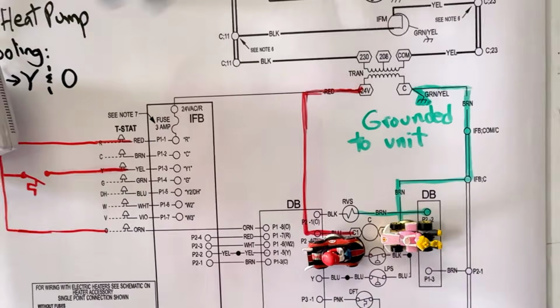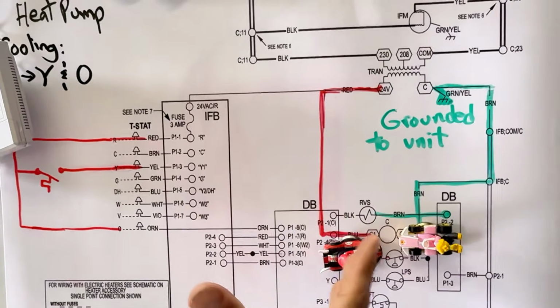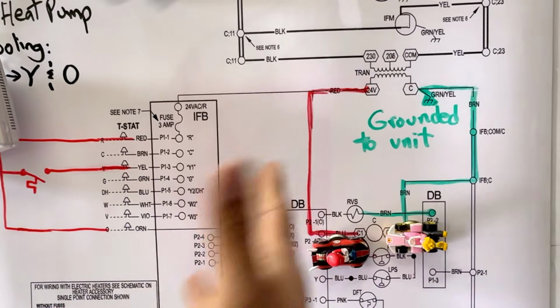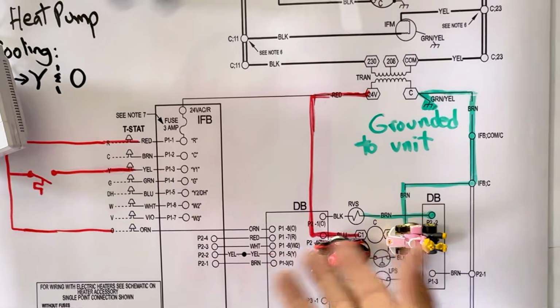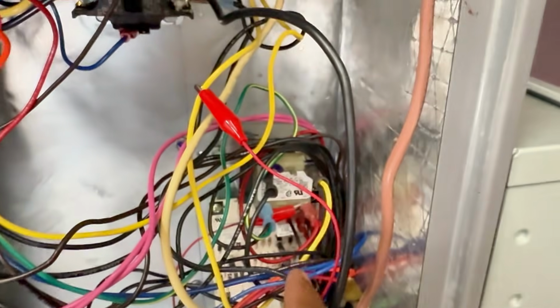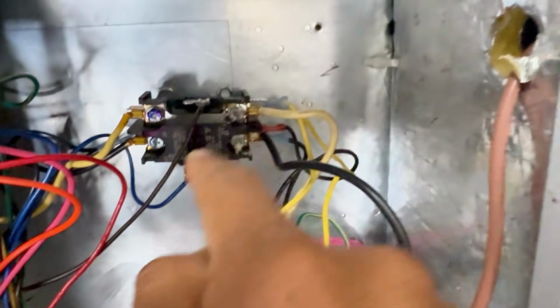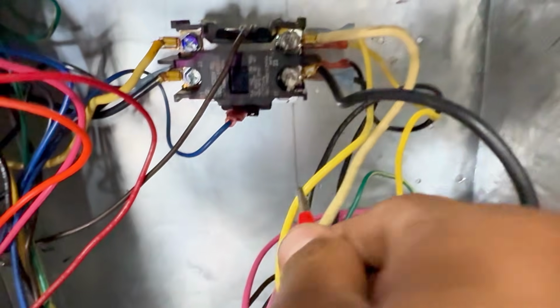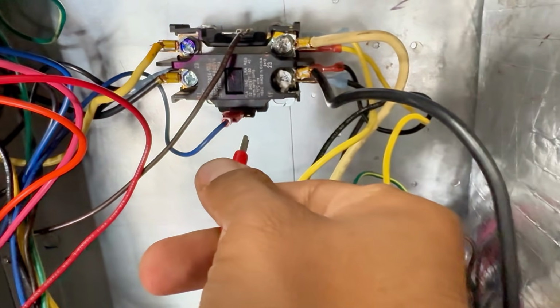Yeah, it's going to work. Even though I'm isolating the thermostat, it's going to work, but the air conditioning system is going to be on 24/7. So this is how it looks right here. Right now, I got an alligator clip, and right there, I'm getting 24 volts, raw 24 volts. That's constant 24 volts. And then my common is my brown one. So the blue one down there, that is my 24 volts.